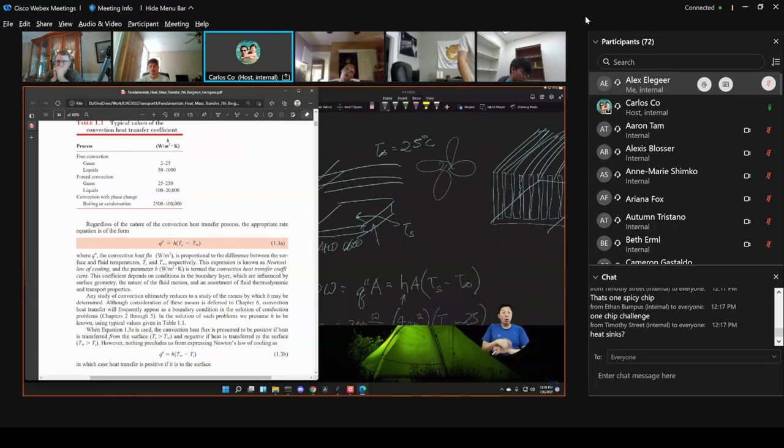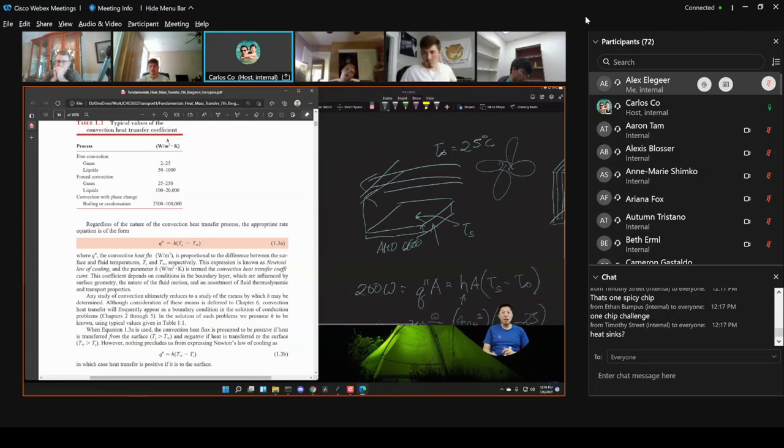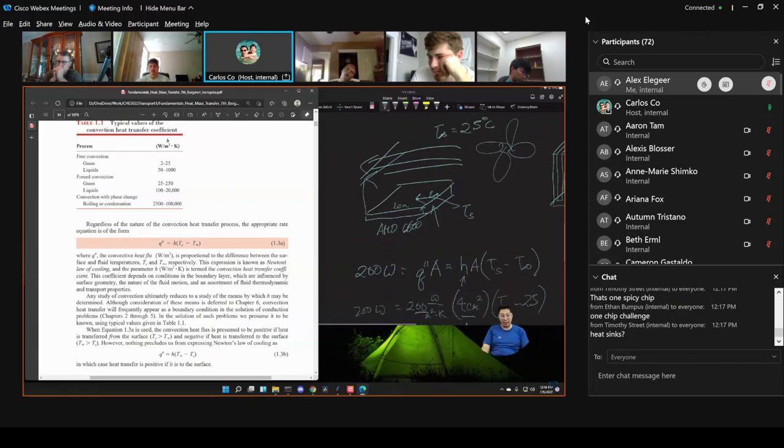Well, what does that do? Earlier our area was 2 cm by 2 cm, which is 4 square centimeters. By putting all those fins in there, you basically increase the effective area, kind of. Of course, it is not perfect, because you expect some temperature drop from conduction through the metal. Usually that's made of aluminum, so it's good conduction, but still there's some temperature drop.